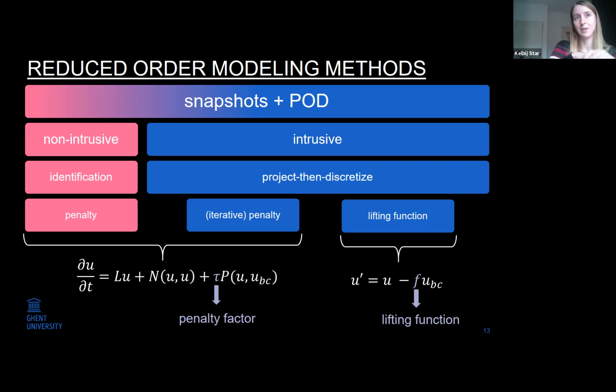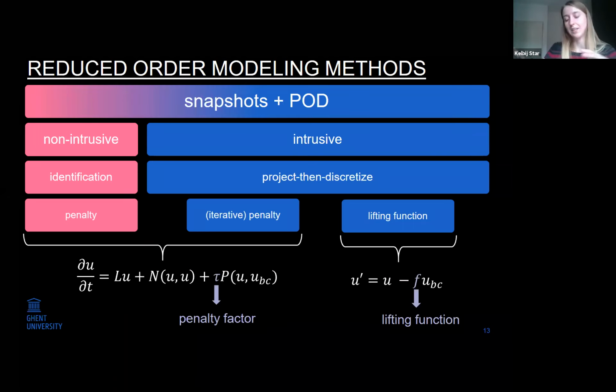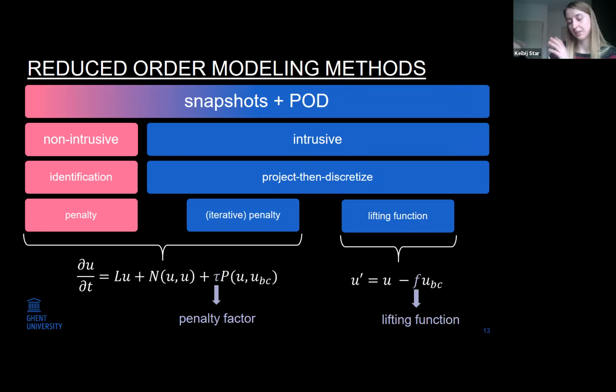The first modes contain the bigger energy scales, and the higher modes contain the smaller energy scales. But you're truncating, and of course everything that you truncate, you cannot solve the reduced order model for, because that information is not contained in it, and that's why it becomes more complicated to solve for turbulence. But as for the number of modes, in my case I was still working even with 5 or 8 modes for velocity and for temperature. So not from that perspective.